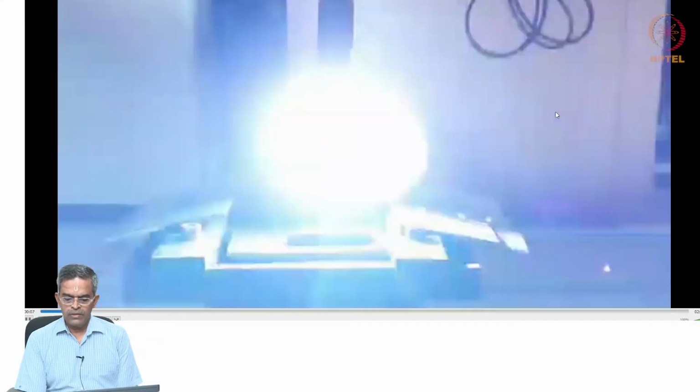So, friends, you can see the CMT torch is doing the wire feed on the stainless steel strata, base strata, depending upon the XY coordinates laid for laying the wire, and the wires are laid in layers, and this is the wire arc additive manufacturing method which you see on the screen at this moment.